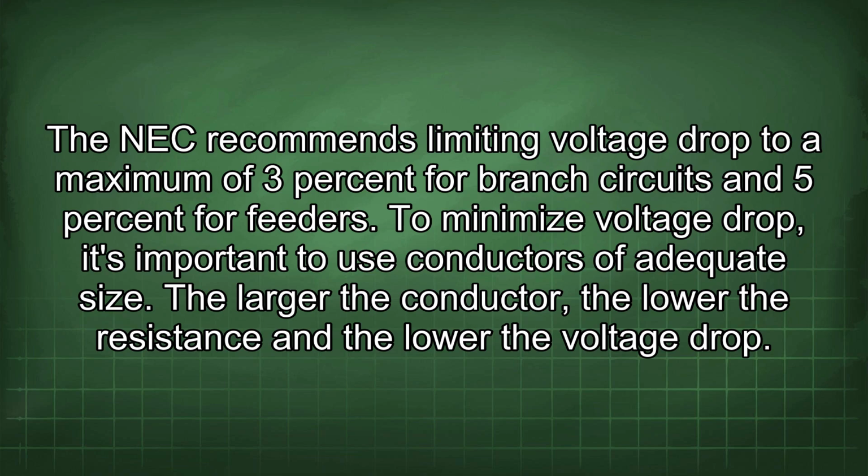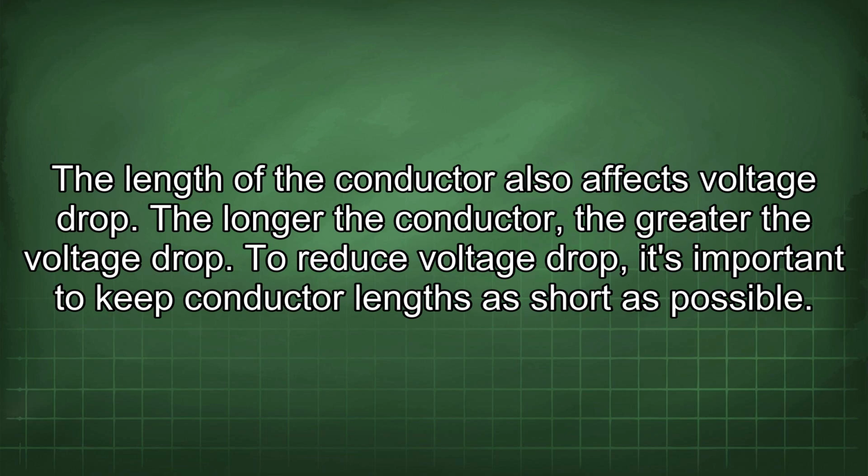To minimize voltage drop, it's important to use conductors of adequate size. The larger the conductor, the lower the resistance and the lower the voltage drop. The length of the conductor also affects voltage drop. The longer the conductor, the greater the voltage drop. To reduce voltage drop, it's important to keep conductor lengths as short as possible.